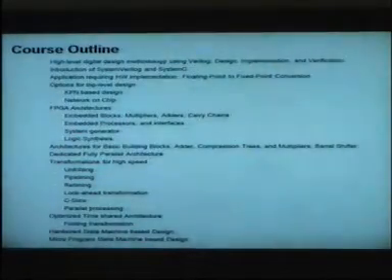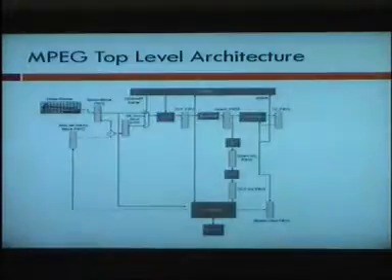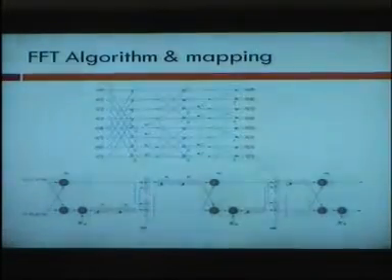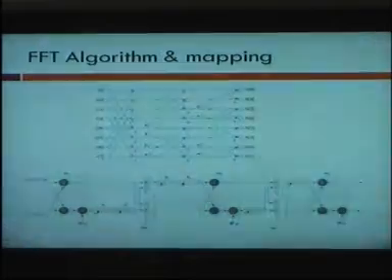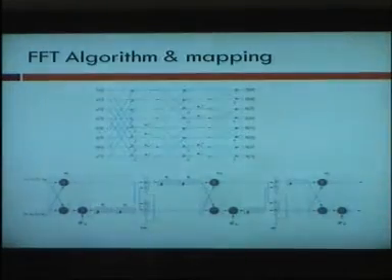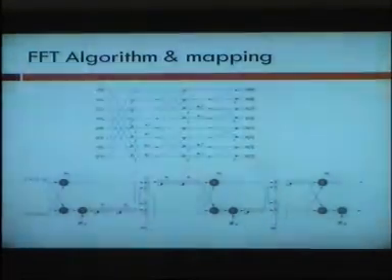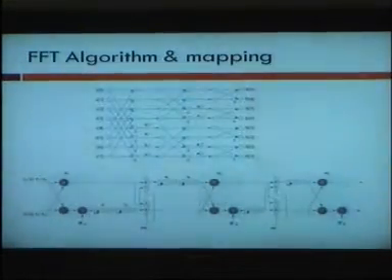Then I'll come to another interesting topic, which is the time shared architecture, where you are folding. Folding means that this is a good design where you have folded the design by 4. By 4 means you are only using 1/4 of these resources. You can fold it by 12 times as well.